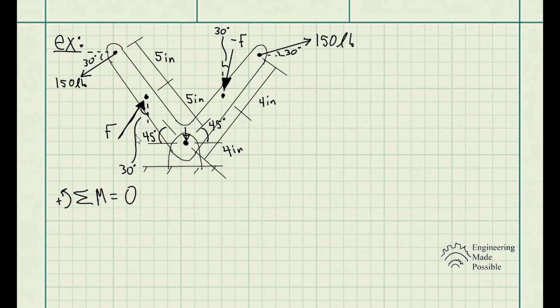Now, this is where you could go force by force and break it up into its x and y components, because keep in mind, in previous examples sometimes only one component caused the moment, but in certain instances such as this specific case, you will have a moment being caused by the x component as well as the y component of every force.